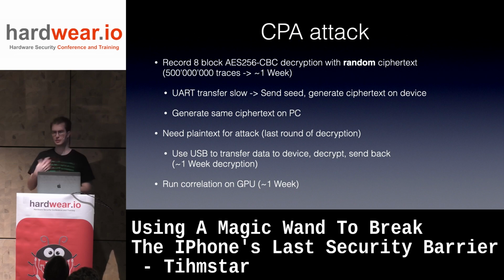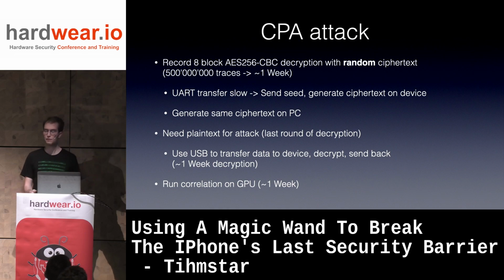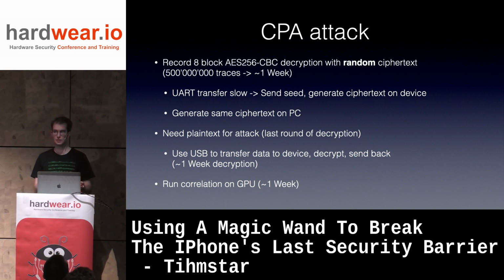I sent over a seed, which would then, using a pseudo-random number generator, generate a batch of ciphertext on the device, which it would run through the AES engine where I could record the traces. And because I have the seed and the same PRNG, I could recreate those on the PC without having to transfer them. Although, because I need the actual decrypted values, the processed values, for the attack, in the second step I needed to send them over all again, and then have the device actually decrypt them, and then store them to use for the attack.